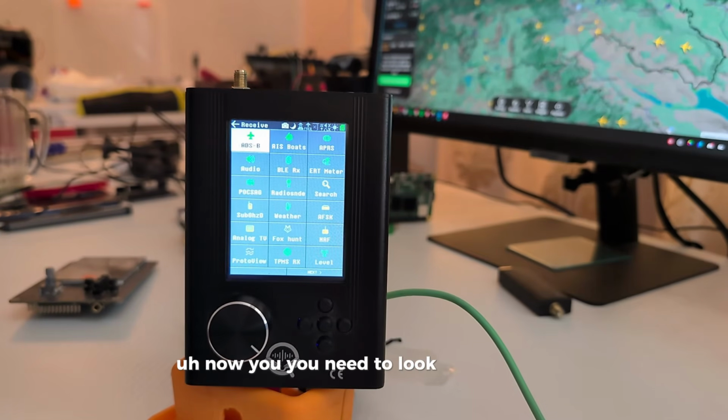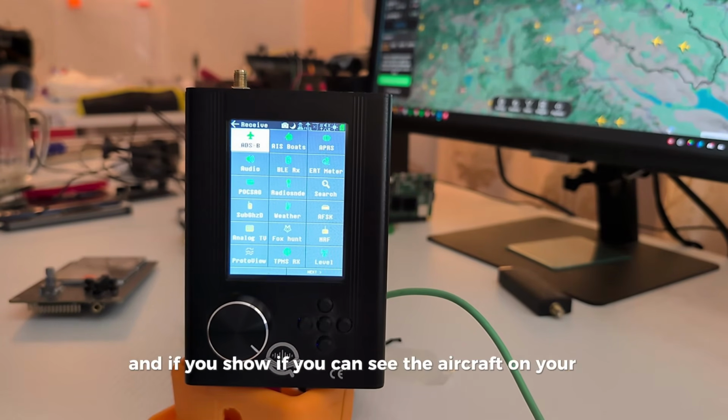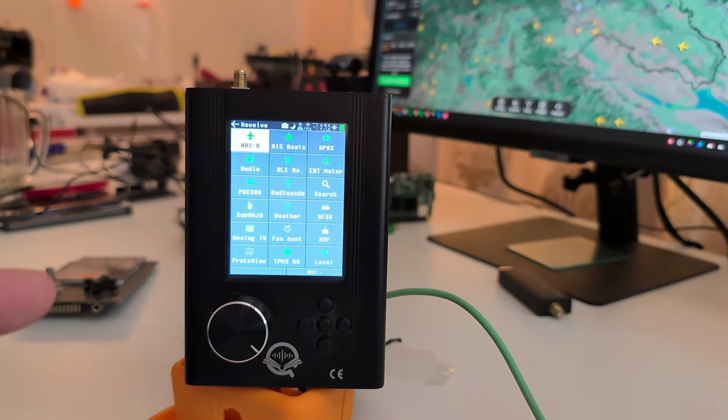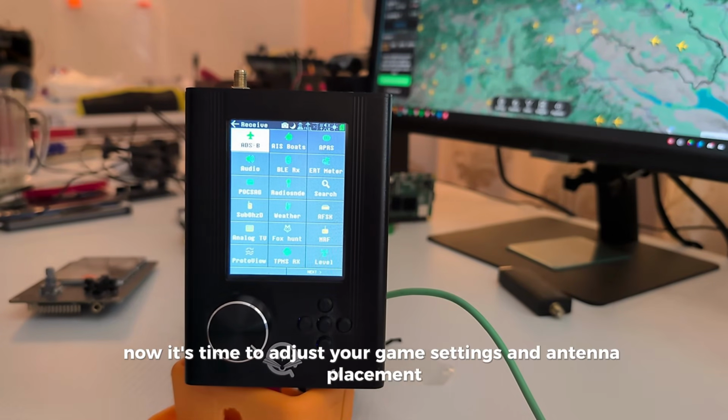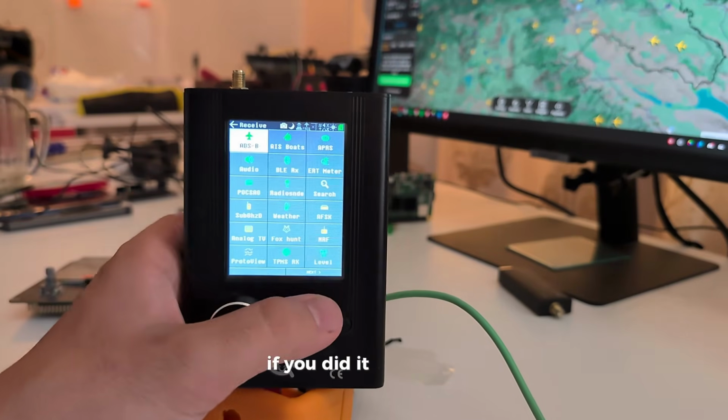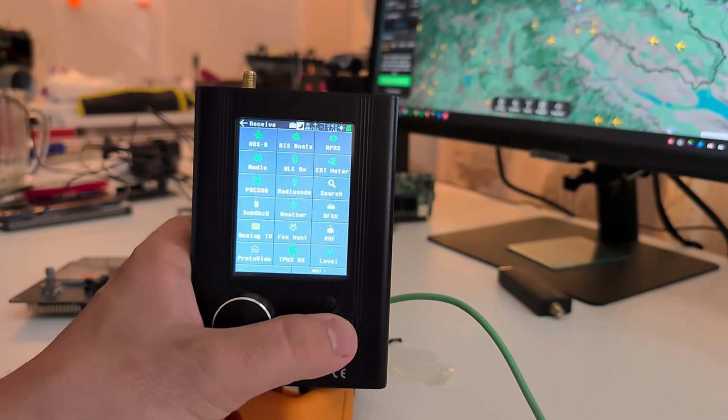Now you need to look at this map, and if you can see aircraft in your area but on HackRF you cannot, now it's time to adjust your gain settings, antenna placement, or check your cabling to see if you did it correctly.